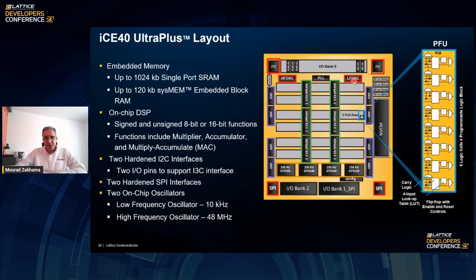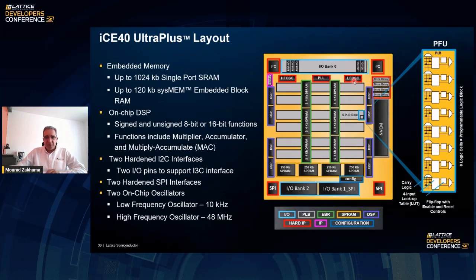We're going to go through all these components in a little bit more detail, without getting into a lot of detail on this, but just to give you some perspective in terms of the complexity that is associated with the architecture of the FPGA. On top of all that, you obviously have the I/O banks. There are multiple I/O banks per device. And you also have some hardened IPs, like the PWM IP that is hardened, or some I/O flexibility or I/O delays that are hardened, and so on. Configuration logic is hardened also. So there are a lot of other features that are available in the fabric.